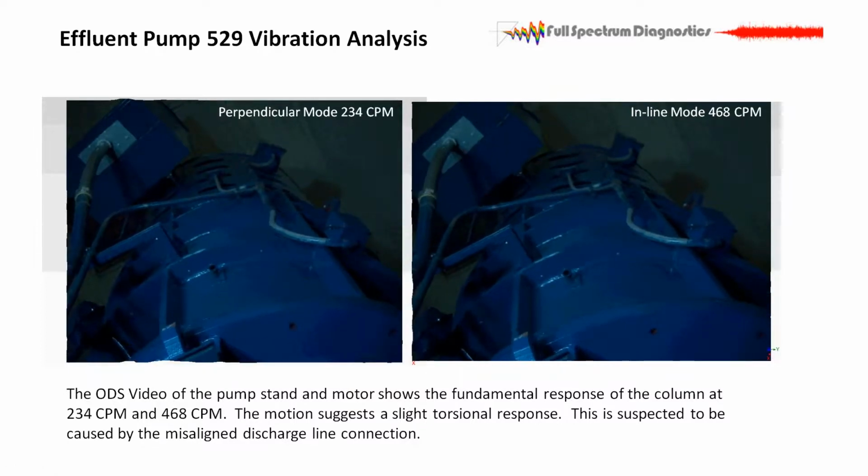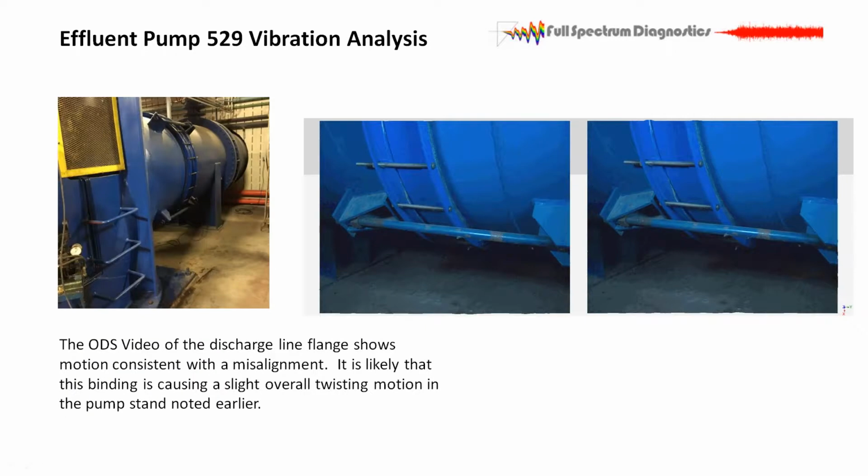Okay, this is that discharge line. It's a very big line. It's what, 60-inch diameter, something like that? Yeah, 60-inch diameter is correct. There's where it buckles up. The two flanges mate right here. They've installed these guides to help it, and it's about 1/4 of an inch off, which is a lot.